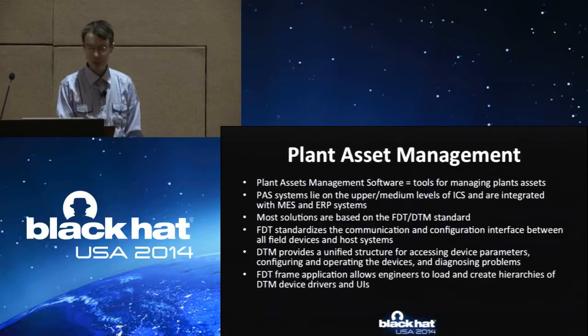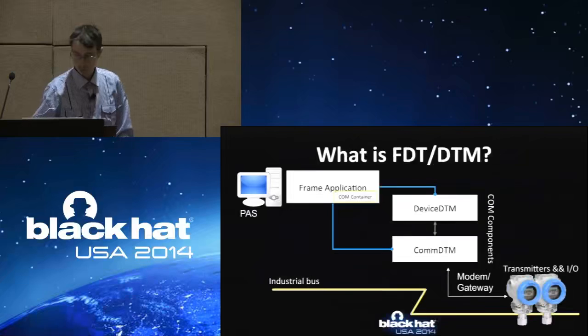Most solutions are based on the FDT/DTM standard. The FDT standardizes the communication and configuration interface between field devices and host systems, and DTM provides the unified structure for accessing device parameters, configuring them, using them, and diagnosing problems. The FDT frame application allows engineers to load and create hierarchies of DTM device drivers and user interfaces.